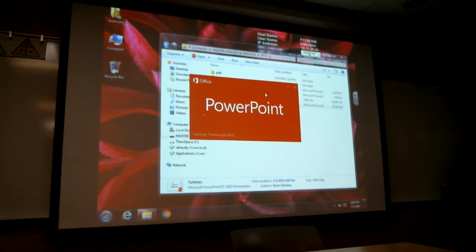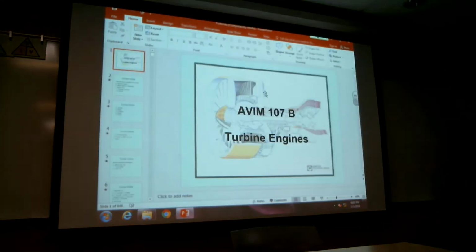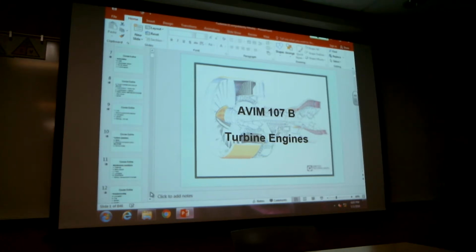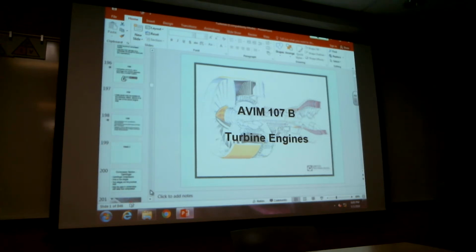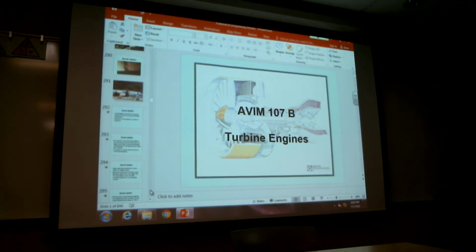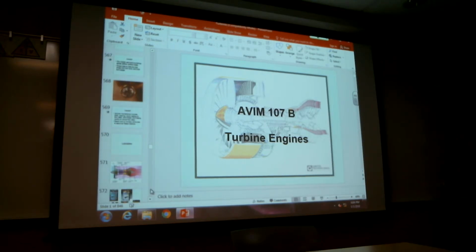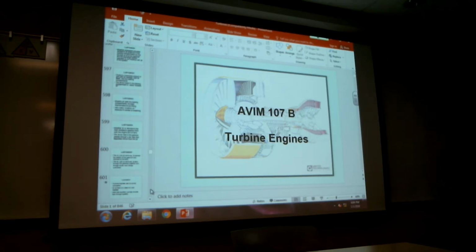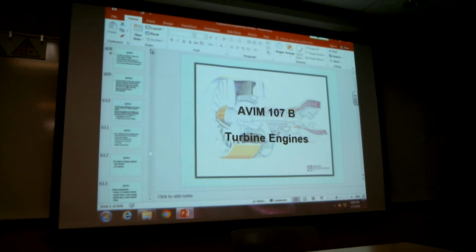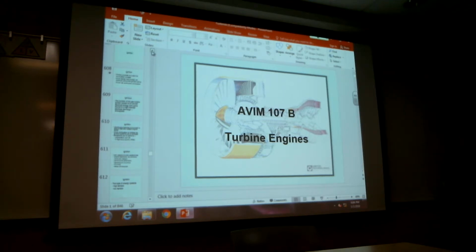Well, we've already increased the temperature of that air just by compressing it. Okay, so now we add this extra heat to it from the combustion chamber. Do we need to keep any kind of a spark going at that point? No. Probably not. Now it depends on the combustion liner. It's a whole range of things that it could depend on, and we're going to talk about those here in just a second.